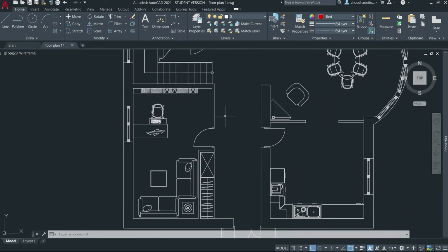When we reach the edge of the drawing space, we will see a bar is displayed on the hand cursor on the edge. Depending on whether the edge is on the top, bottom or on the left or right side, the bar is either vertical, horizontal or on two sides of the hand. There are other ways to access the pan command which we will learn in the later videos.